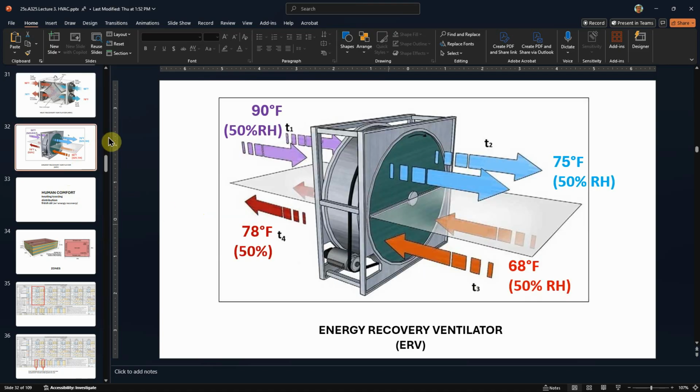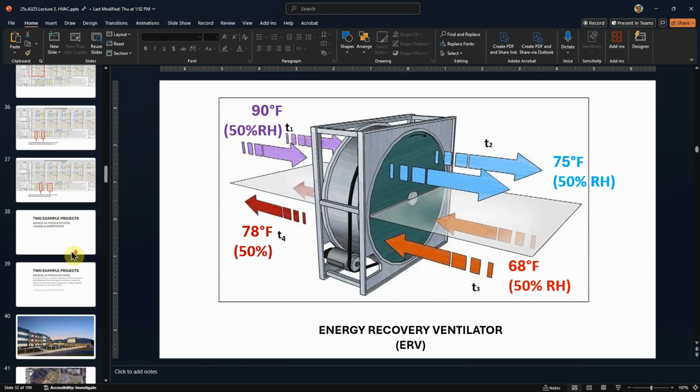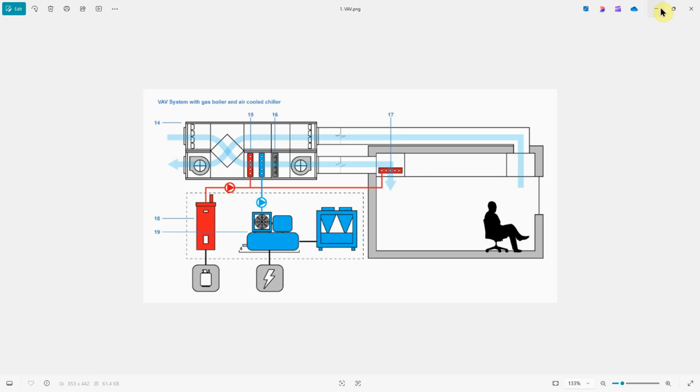Remember, the basic idea of energy or heat recovery ventilation is this: it's hot or cold outside, and we've spent money getting a stable temperature inside. We've got to take some of that stale indoor air and exchange it with fresh air. Of course, as Professor Theodoridis has said, that's way too simple. But the concept is we have to exchange air, and we have these devices that allow us to save energy as we do that, and not just bring in 25-degree cold winter air and have to reheat it from that baseline temperature. Anyway, there's tons of other information in these slides that's related to this.